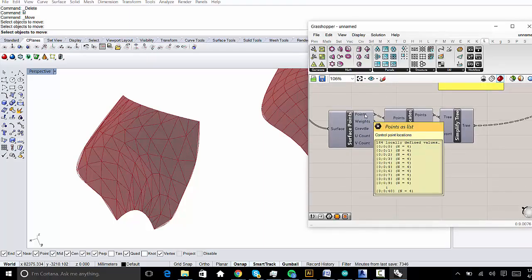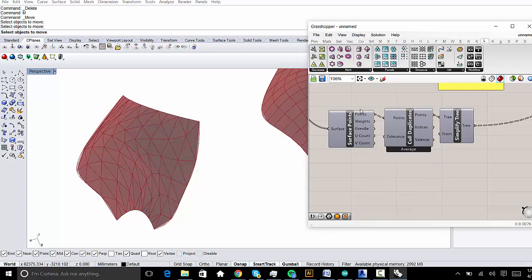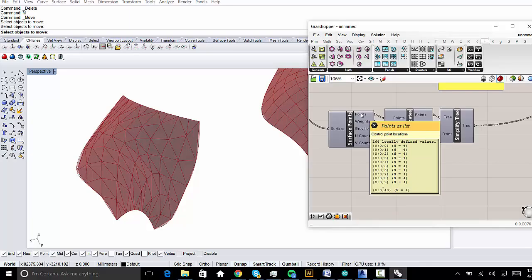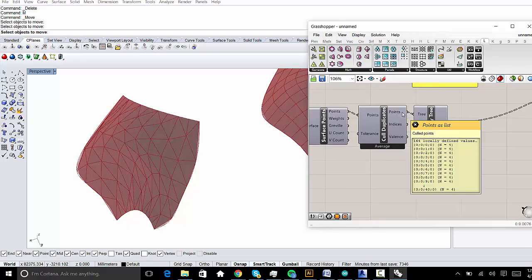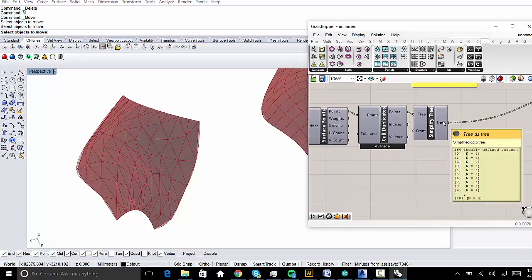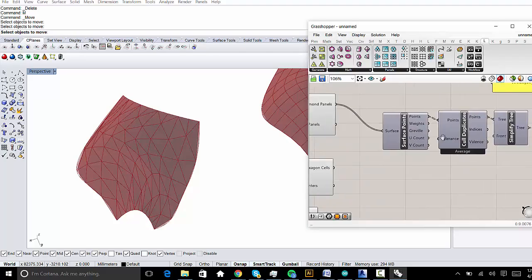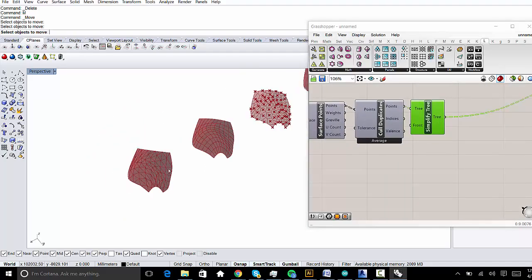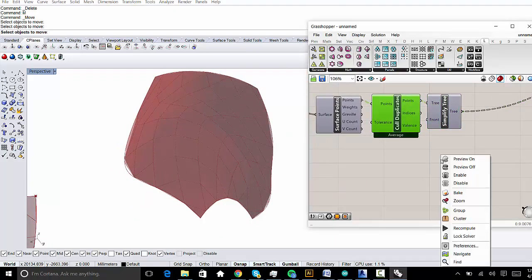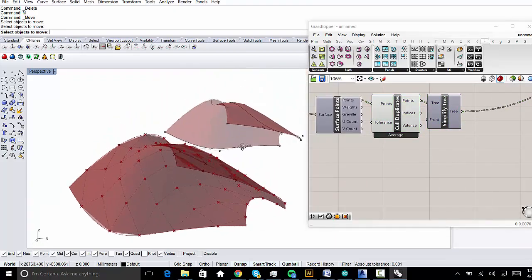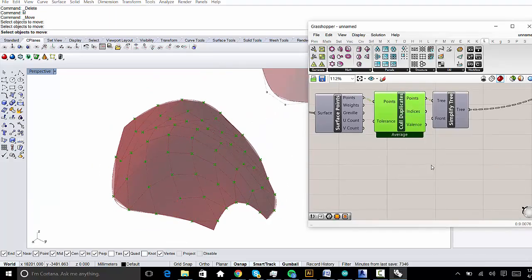You can see that there's 164 values in a list of 41 lists, each with 4 corner points, and the duplicates, there weren't any, so you end up having a nice list of 4 corner points for each panel here. If I look over here, that's what's right here. Turn these on. You can see my corner points.